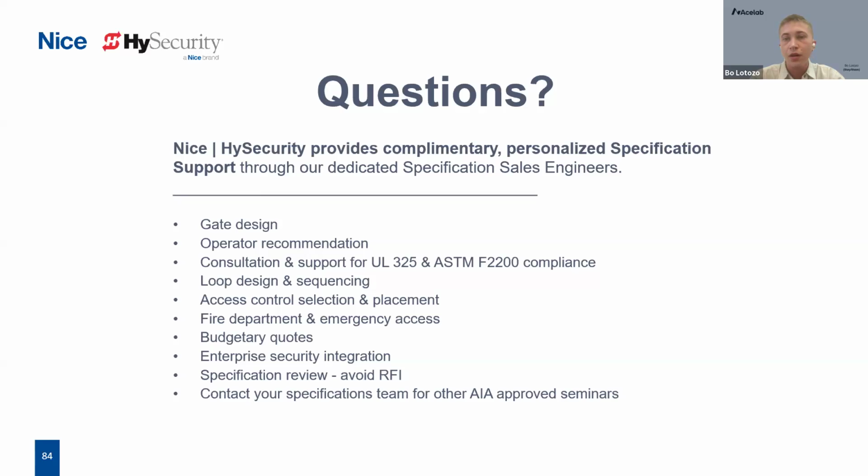Could you touch on how these systems can handle emergency vehicle access while still maintaining security? Yep, I mentioned earlier that we want to always reach out, and we will remind you to reach out to the fire marshal during our initial conversations to see what kind of emergency access control device they want and where they want it. They're going to tell us. There's some pretty neat options out there nowadays besides that good old-fashioned Knox firebox, that big red box. So we want to make sure that we're including their required emergency access device and where they want it.